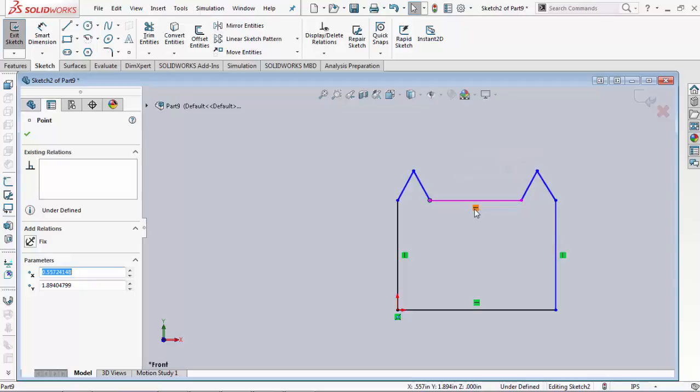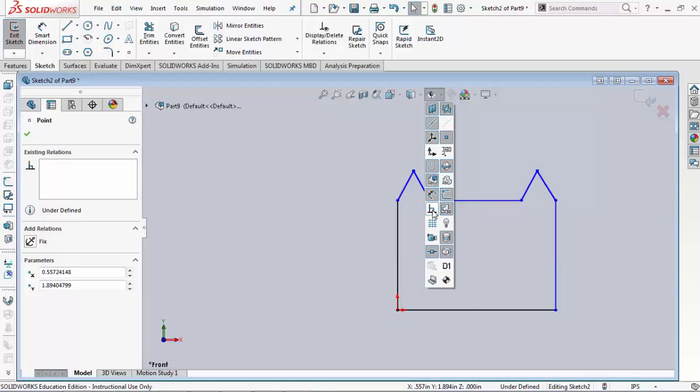From then, notice that the last 4 constraints that I have are vertical and horizontal constraints, which is what I wanted, so that's good. If for whatever reason you are not seeing these, you can choose to come over to the little eye here for visibility and click on this little icon, and you can turn the visibility for your constraints or your relations on and off using this button.